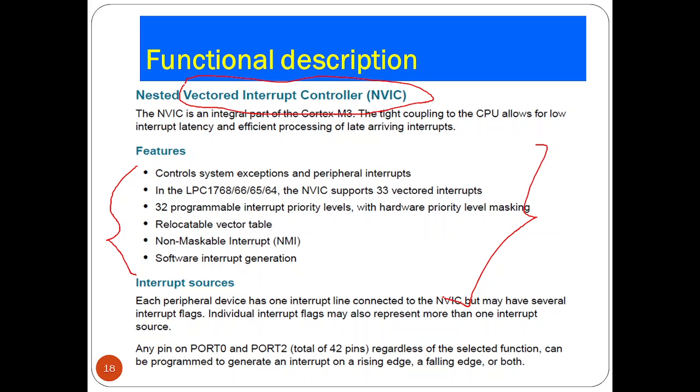So that is going to be one type of process which is always available in all types of controllers. For calling the interrupt, restoring this, and completing that unit, you need a maximum time. That time is reduced by using this type of nested vector interrupt controller. Initially that time is more, but in this nested controller it reduces, and that's why switching of a device from one working to another is a very easy task.